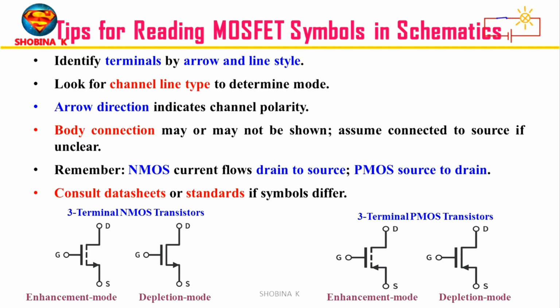And next, body connection assumptions. In many schematics, the body or substrate connection is not explicitly shown. When it is not shown, assume it is connected to source. If the body is shown separately, note any special connections that affect device behavior.